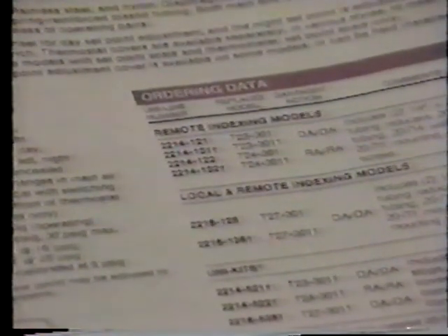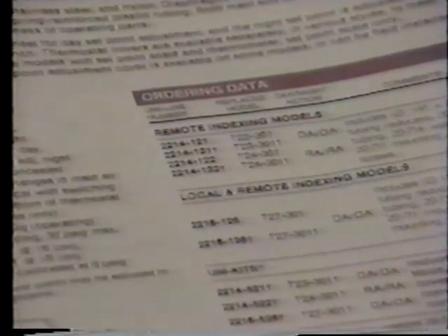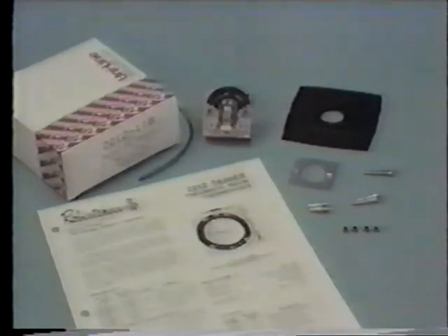This is the Uniline Pneumatic Controls Catalog. The catalog provides device specifications, typical piping, part numbers, and replacement listings for original equipment models, including the control action and parts included. Shown here is a model 2212-118, direct-acting, two-pipe room thermostat with the accessories that are packaged with each device. Mounting requirements may vary depending upon the type of thermostat being replaced.